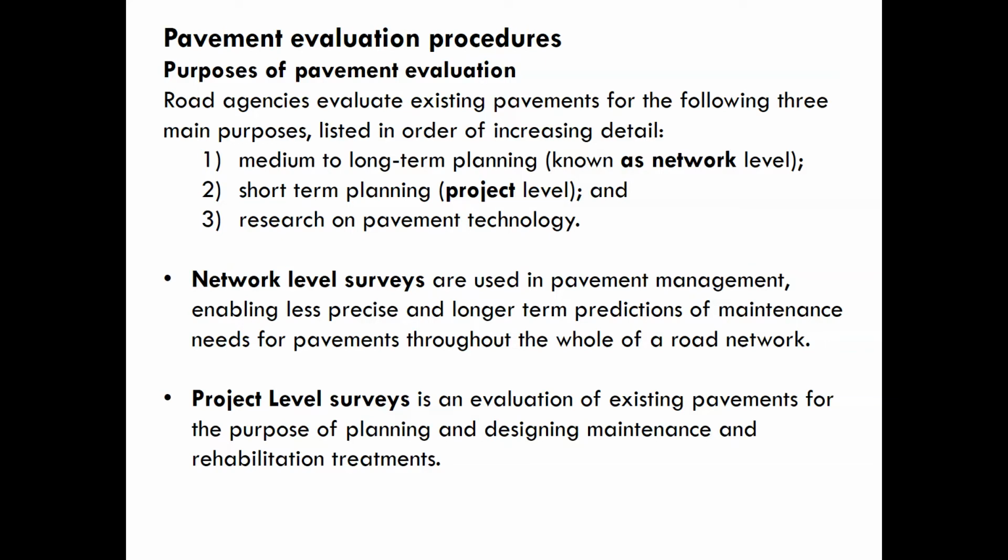The purpose of the pavement evaluation is that they have three main purposes, listed in order of increasing detail. They have this network level and project level. The network level is the medium to long term planning, and the project level is short term planning.